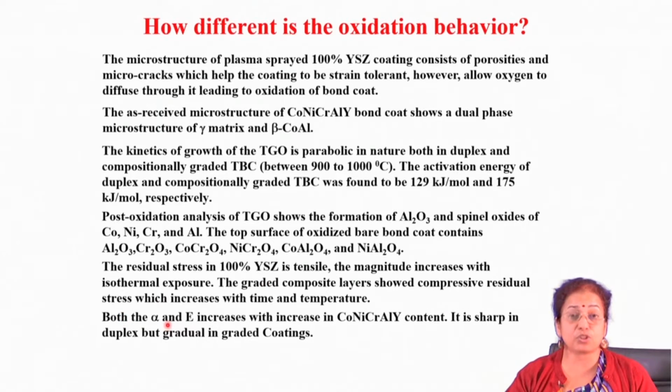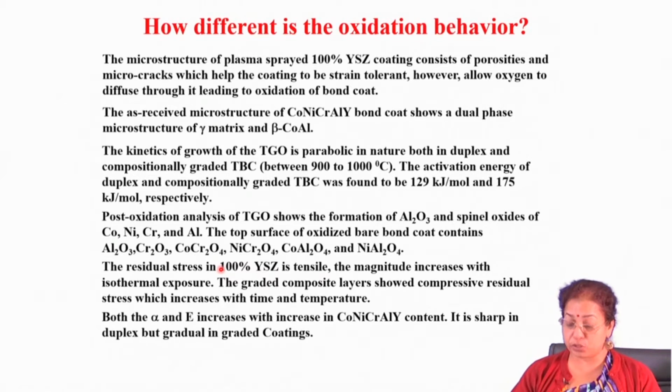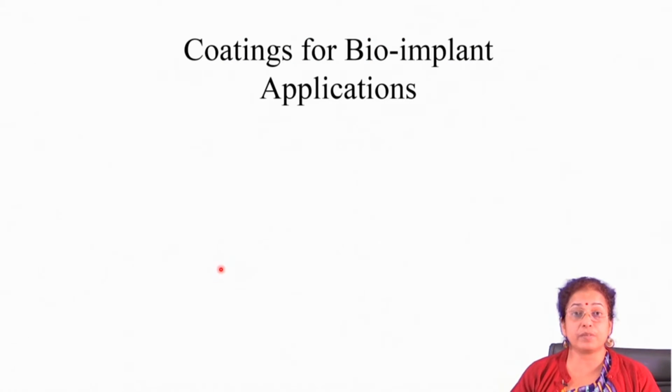We also found that the coefficient of thermal expansion and E value increase with increasing CoNiCrAlY content, and naturally it helps in reducing the stress level. Like that, we also tried to develop a ceria zirconia and lanthanum mixture, and observed that this composite coating offers superior oxidation resistance than the typical duplex coating.